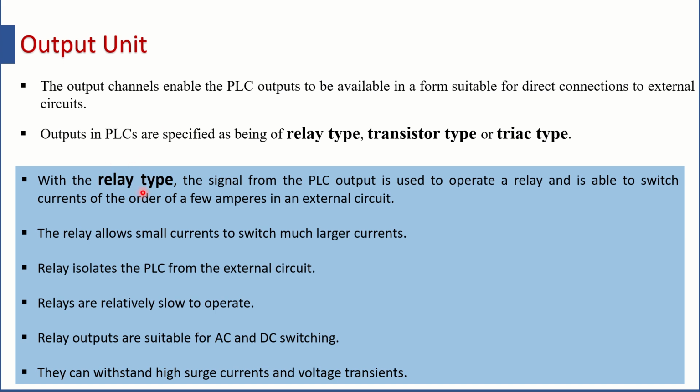It will be given to the solenoid part of the external relay, so that the PLC signal can simply activate the solenoid. Now, when the solenoid is activated, the NO, NC and common terminals are available to you for the final connection.